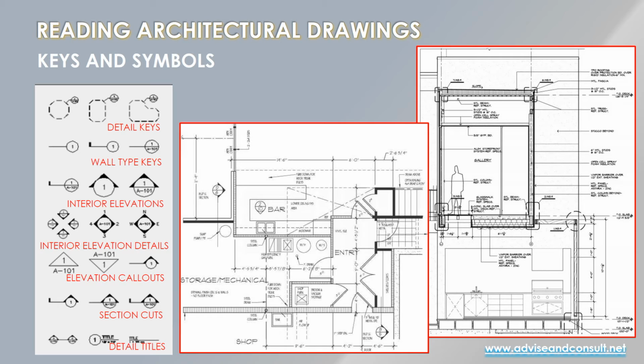So that helps direct you forward, whereas interior elevations and wall sections or section cuts are identified by these dark arrowed circles. Again, the same idea. On the plan drawing in the middle here, you'll see a section cut in the lower right-hand corner called B5. That is identifying detail B on sheet 5.